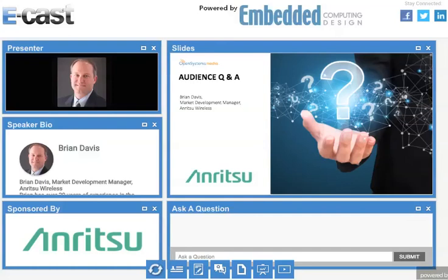Okay. Looks like we got time for one more, Brian. Can the Enrichment equipment do CDRX testing? I need to test power and sleep consumption on my device. Yeah, so DRX testing, we have that ability. You can set the long sleep delays, short sleep delays, wake-up timers, paging information. So if you want to set your device to be on a long DRX and force it to sleep for a long time, we can do that, or short sleeps.